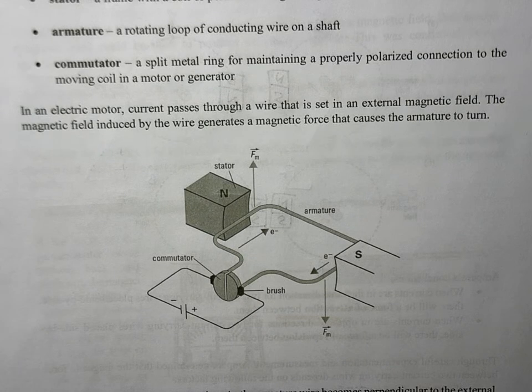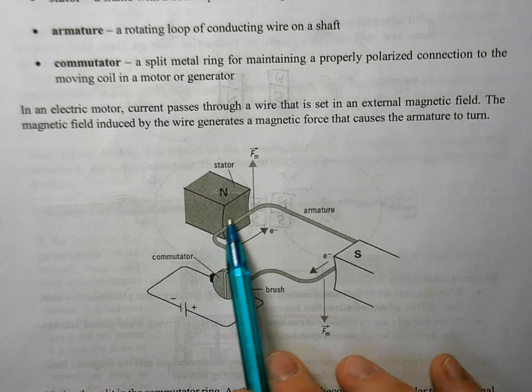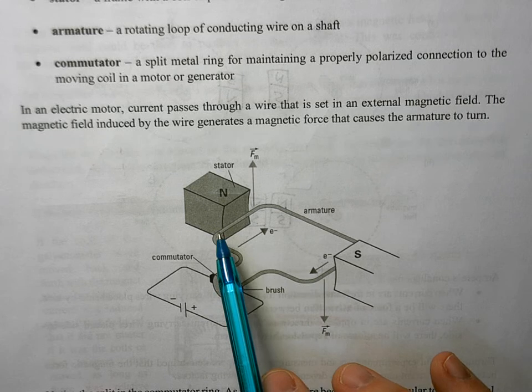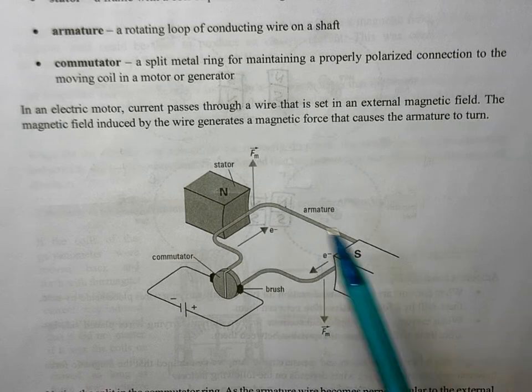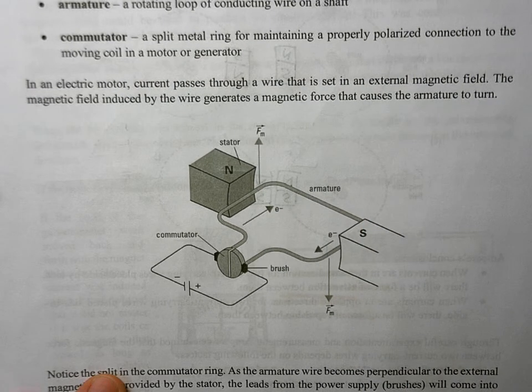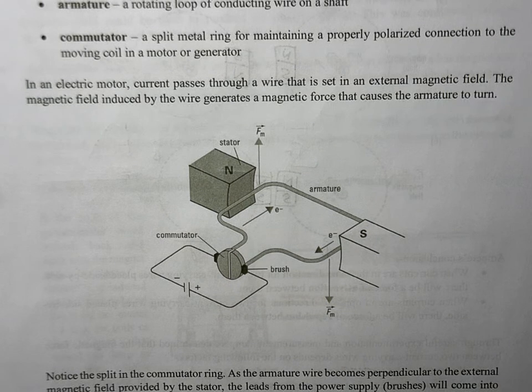What's really important for the armature wire is that it's bent such that the current is still going in one direction through the wire, but as it passes through the magnetic field it changes direction, because you'll see here it's going in this direction, but down here it's coming this way. This ensures that the magnetic forces on different sections of the wire go in opposite directions. A torque can be generated on the wire, and then that armature wire can spin, and we can use that energy for whatever purposes we desire.